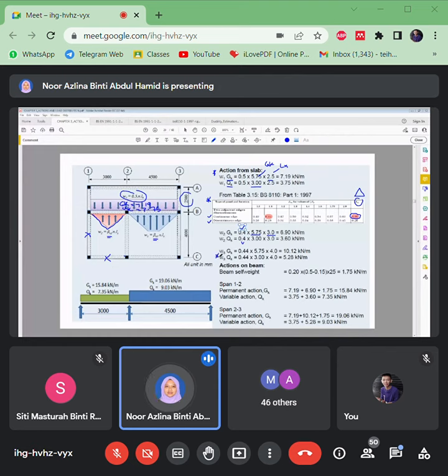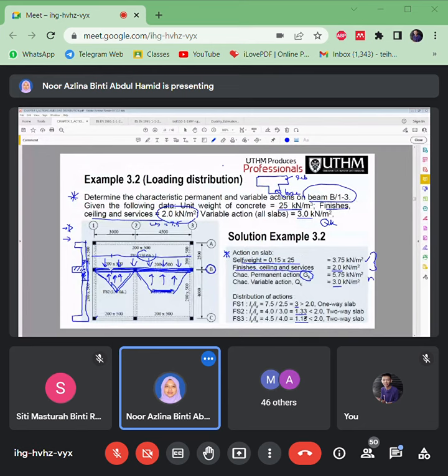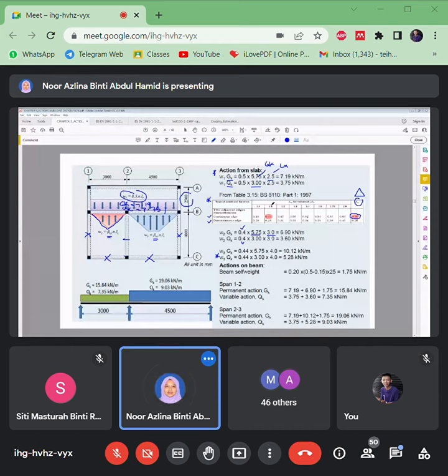So for panel 3 it is the same, the same case here, which is one long, one short, discontinuous. The rest are continuous. So you also refer here. But this is a trapezium. So for the trapezium you need to know the value of Ly divided by Lx here. Okay, look at what was calculated earlier: 1.13. 1.13, which is the nearest one.